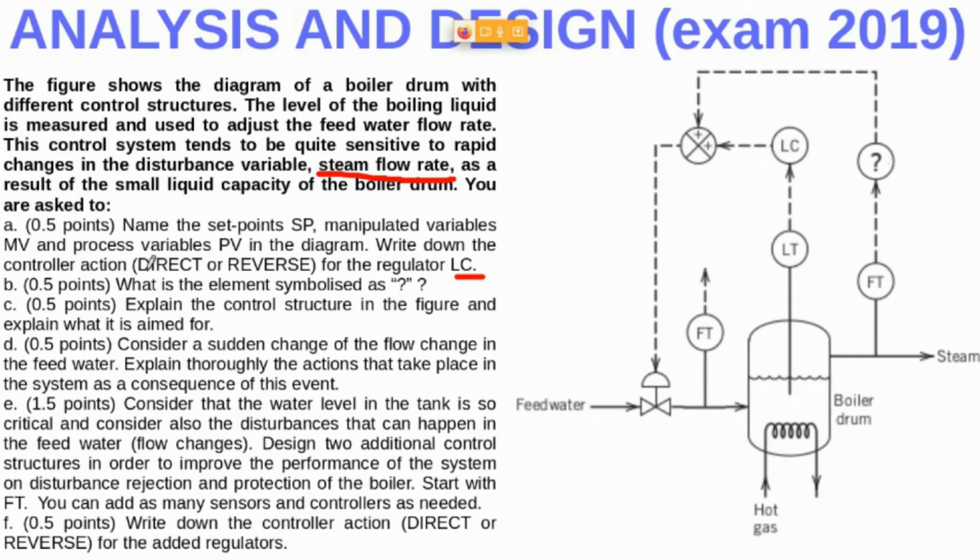Then the set point, manipulated variable, and process variable are very easy. As you can see here, we have the measured process variable. So you can say that here we have PV, here PV star, in order to make the difference. But at the end, remember, this is only a translation in an electrical form of this physical variable. These centimeters will be translated into volts or amperes. This is the controller action, and finally, this controller action is applied to the admission valve.